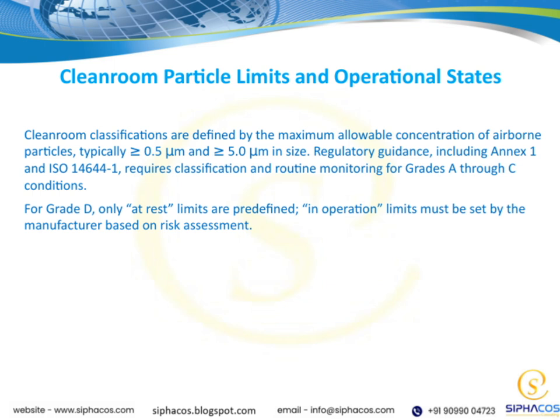Regulatory guidance, like Annex 1 and ISO 14644-1, sets out the standards for these classifications. They require not only defining the class of cleanliness, but also routine monitoring to ensure ongoing compliance. These standards cover grades A through C conditions, which are typical in many controlled environments.